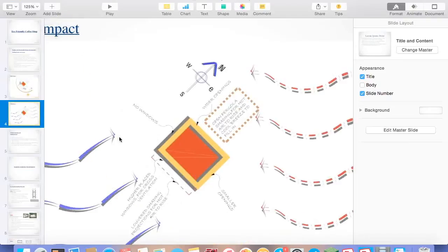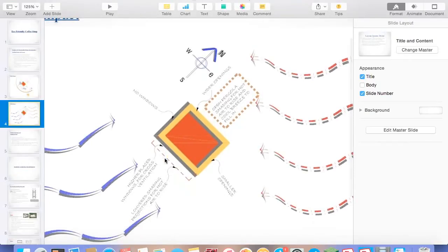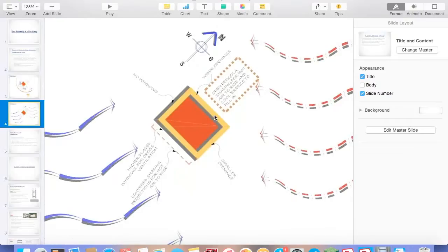Let's look for the wind direction. So here, if we have open pergolas, semi-shaded seating along with some water features, it will be good because the breeze will flow mostly from northeast to southwest, and then we can have windows in the opposite directions but taking into consideration the solar path as well, so that we have very good air circulation.